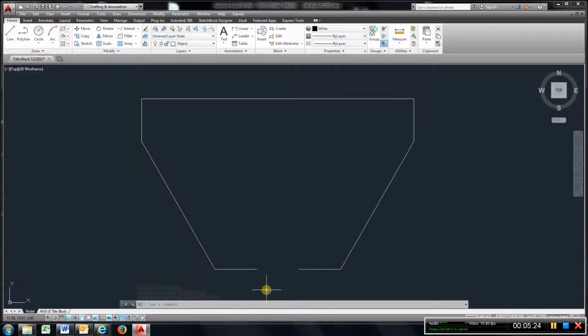Now, I'm going to have to come up. If I look at the very top, I went down 1 inch to get to the top of that T, and I need to come down 1 inch again. So I know that these two lines are 2 inches high. So 2, enter. Line, 2, enter. And my T is 3.5 with a 1 inch space here. So each side is going to be 2.5, so I know these are 1 1/4.